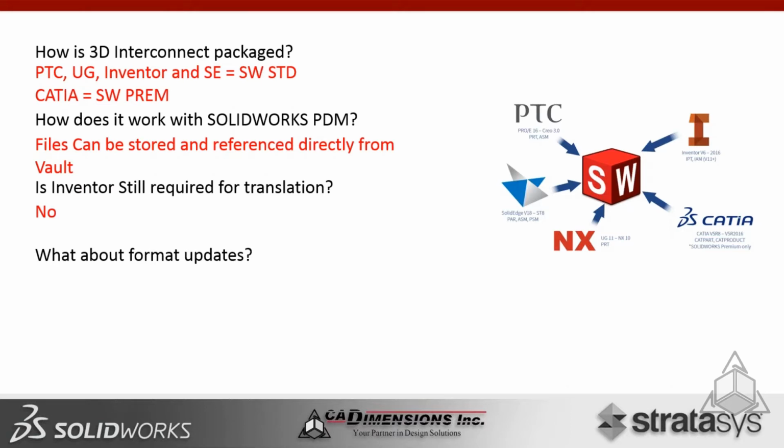Is Inventor still required for translation? And the answer is no. I showed you earlier when I went to open an Inventor file, it said it's unsupported. Well, it didn't see Inventor on my system. It didn't see Inventor View. With Interconnect, you no longer have to have Inventor. You can now turn that on and open Inventor files to bring them in.